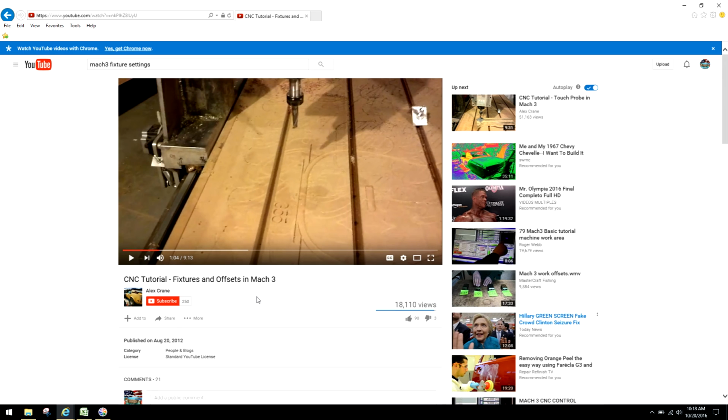That, however, I get questioned on home switches. Well, let's talk about home switches. If you're planning on machining the same project over and over again in the same location, maybe you're cutting out, I did a video on the demo CNC business model, maybe you're cutting out an RC car chassis or a shock tower, whatever it may be, and you want to cut 100 of those parts out and just load raw material into the same location on the mill and have it start milling at that general location, and considering that home.